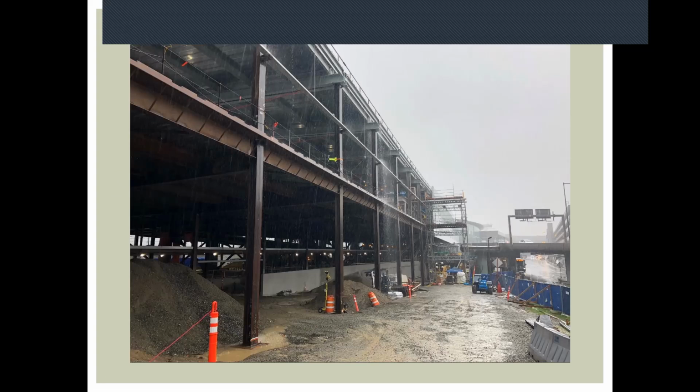It's a massive project, and roof drainage probably would have been very difficult to deal with, but on everything from housing developments to concrete tilt-ups or anything like that, just be aware that when it rains, at many stages of construction, you're going to have a lot of clean water draining off and draining into bare dirt probably. So keep that in mind and figure out ways to have the contractor collect the water and pipe it to storm or wherever it's eventually going to end up when the project's done, just to keep it off the dirt.